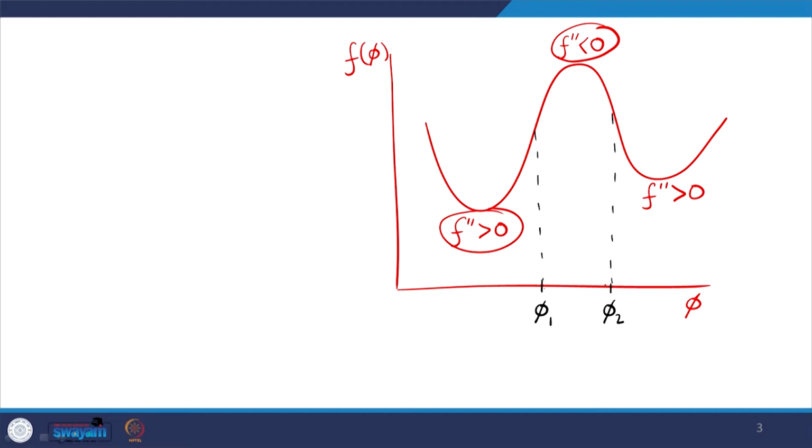And the answer is that they will lie along a common tangent that we can draw like this in the graph, that is basically a tangent to the two minima points in the curve. And these points, let me refer to them as phi A and phi B, will be the volume fraction of the two coexisting phases.